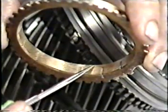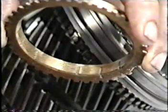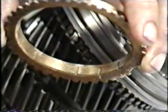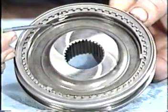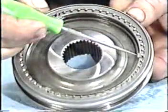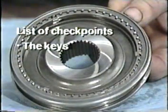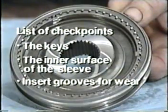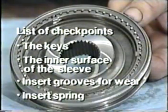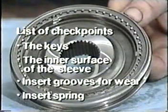Here's an example of a worn synchronizer ring. The inside grooves are worn smooth, and the ring won't grip the gear cone. You'll definitely need to replace the ring. Now inspect the rest of the synchronizer assembly to see if it has any other problems. Check the keys, the inner surface of the sleeve, and the insert grooves for wear. Also, inspect the insert spring for tension. Looks like only the ring will need to be replaced.